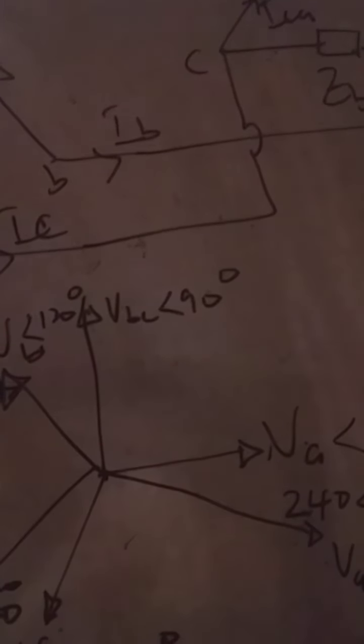IA, and if you use Kirchhoff's current law, you look at all the currents, the summation of all the currents approaching and leaving this node. IA is going into the node, we can take it as positive, the one going into it as positive. The one going away, IAB, as going away. ICA is going into it, so we take it as positive. And IAB moving away, minus IAB, is equal to 0. Summation is equal to 0 according to Kirchhoff's current law.